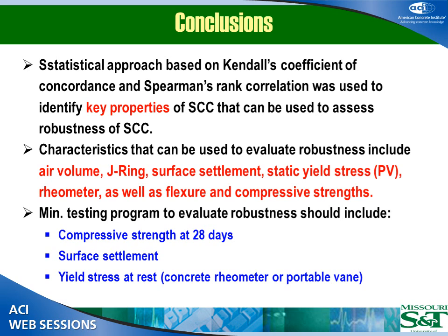Okay, the question is why do we choose plus and minus 1% on changes of humidity of the sand versus 10% on the super? If you look at many recommendations, you can even look at some of the reports from NCHRP, etc., these are within production variations. For example, if you're using 900 kilograms per cubic meter of sand and you're changing that plus or minus 1% humidity, that means it's plus or minus 9 liters of overestimation or underestimation of water.